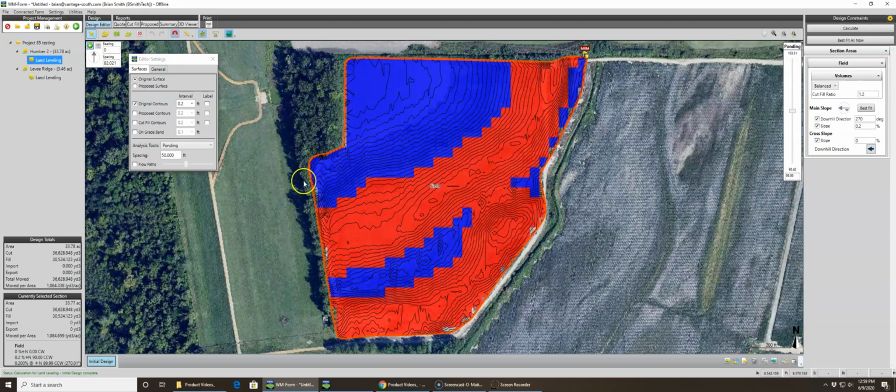Okay, ponding. So at an elevation of 99.96, this is how much water would be covering the field at that elevation. Okay, these elevations are relative to the master benchmark elevation. The master benchmark elevation in this is 100. Okay, so if we put this on 100, well, let me just type it in there. That much of the field would be covered in water. Okay, that you can tell how much of your field it will be covered.